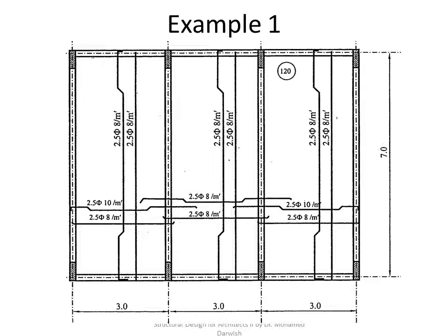You bend the bars, by the way, in Arabic they say يكسحوا السيخ. السيخ تم تكسيحه. Okay. So when you bend the 2.5 phi 10 from one side and 2.5 phi 8 from another side, you get the same result, 2.5 phi 10 plus 2.5 phi 8 above the support. Then at the midspan, it's 2.5 phi 8 and 2.5 phi 8.